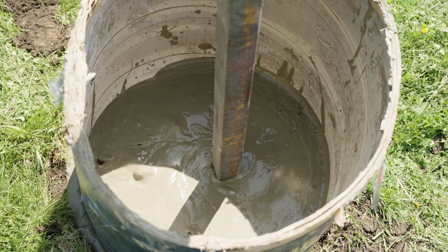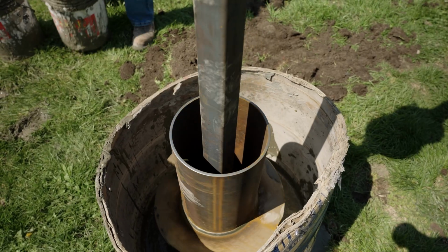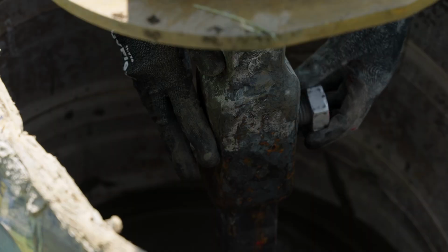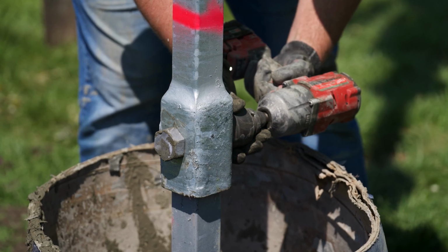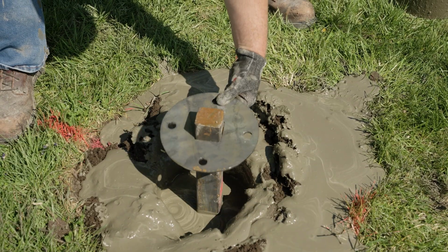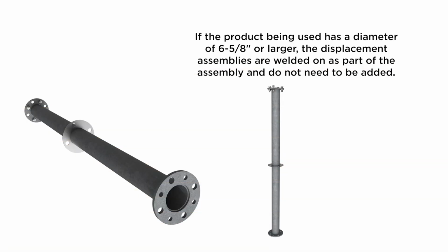The volume of grout contained in the reservoir must be maintained at a level sufficient to maintain positive hydrostatic pressure on the grout column. Extension sections are added to obtain the required minimum overall length as shown on the project plans. Extension displacement plates are added at the connection of each extension section to maintain grout advancement and to centralize the pile shaft. If the product being used has a diameter of 6 5/8 inches or larger, the displacement assemblies are welded on as part of the assembly and do not need to be added.